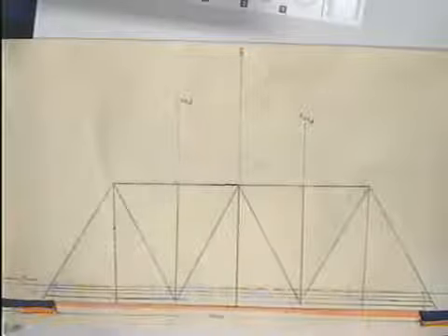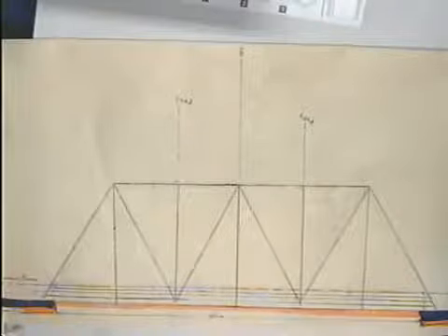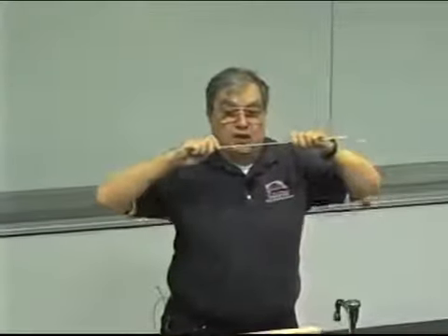You're going to get basswood like this, really thin basswood. Now, a couple things about this. It's really strong under extension. I can pull real hard on this and nothing's going to happen. What happens if I push on it? It bends and it breaks. It is fairly strong under compression. That's compression. If I take a short piece, it's much harder to make it bend and break.